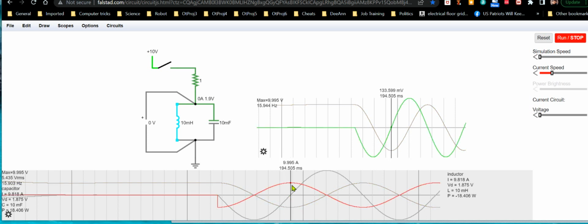So the capacitor will try to supply a larger and larger current to that inductor because the inductor demands it. But at some point, when we reach this point here where the voltage is zero, that means the inductor is fully charged and the capacitor is fully discharged. There's zero voltage, so it effectively doesn't have any energy, but its current is still considered maximum.